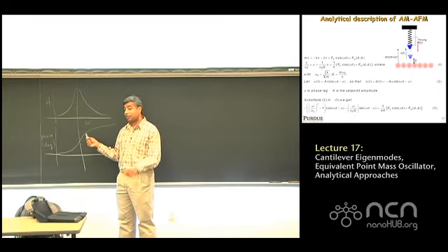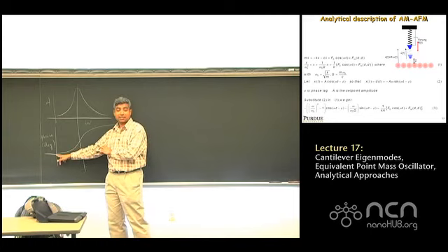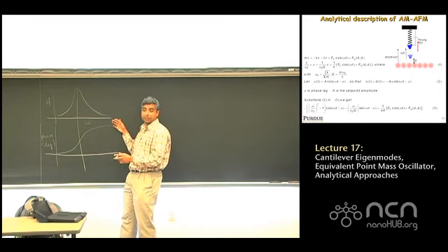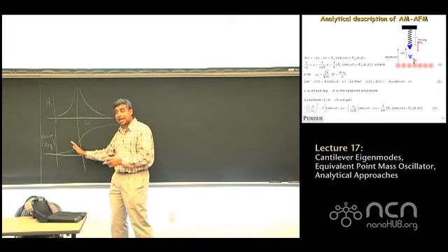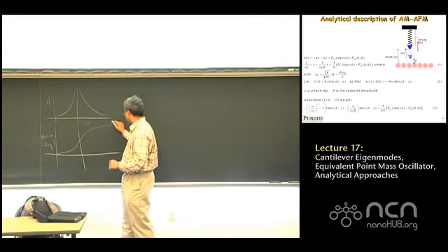Going back, we have studied these resonance curves before. This would be phase lag, because what it means is when you're far below resonance, it's lagging very little. And when you're above resonance, it's lagging by a large amount. So it's going to be the phase lag that increases across resonance. On the other hand, so this would be lag.